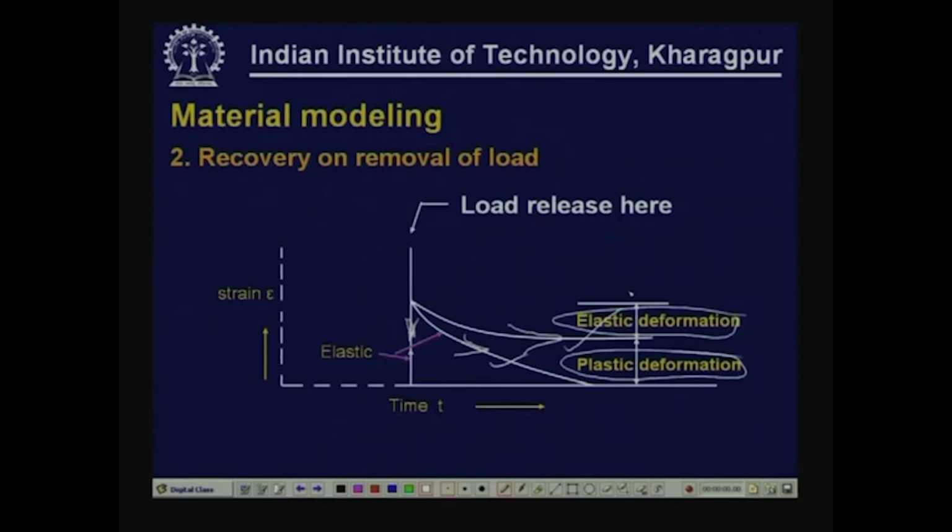So, depending upon the materials that are used, different materials will have different behavior, but hardly any pavement material can be considered to have instantaneous recovery. Most of these materials recover to a great extent depending on the condition to which they are subjected, but most of the recovery is over some time period.